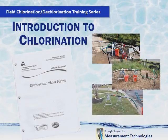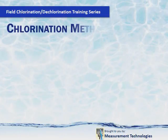Times are a-changing. With the newly revised C651 chlorination standard and the implementing of dechlorination requirements, procedures that have been used in the past will change in the future due to the revisions. With increased flushing requirements and the need to neutralize all your discharges, chlorinating properly becomes even more important now because of the cost of dechlorination.